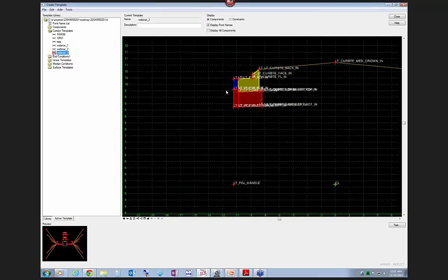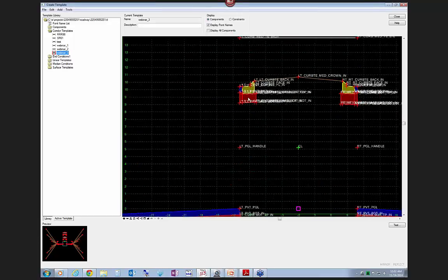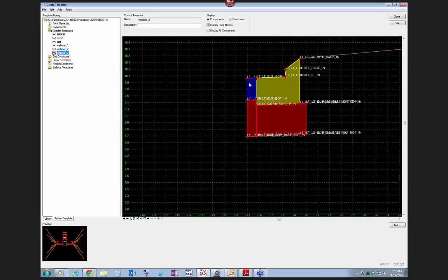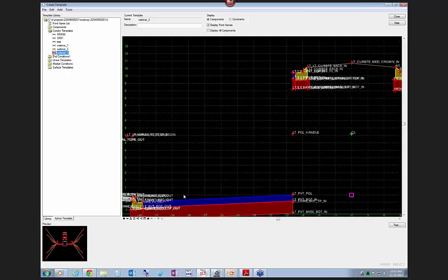The other thing about vector offsets, and this is going to be hard to explain, but essentially if you want a turn lane to follow the same super elevated slope as your pavement, you don't necessarily have to add a super elevation section to this lane. You can use what's called a vector offset on the constraint of this slope.